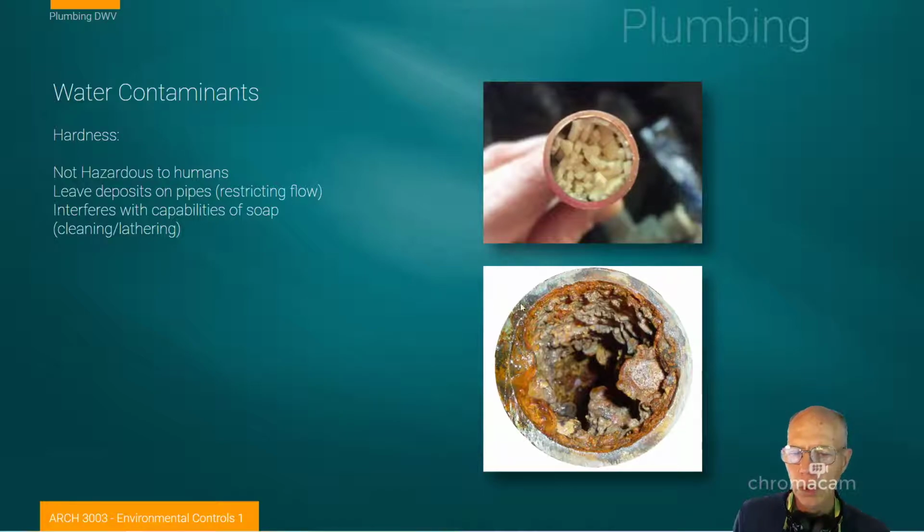So in this case, we're looking at cross sections of pipes, and we're looking at the growth of minerals and other sediments inside of the pipe, corrosions. And the negative effect here, and the one that an architect would be concerned with in the long term, is that the pipes become so full of mineral scales on the inside that they can no longer pass fluids, the water, and we need to repair the plumbing.